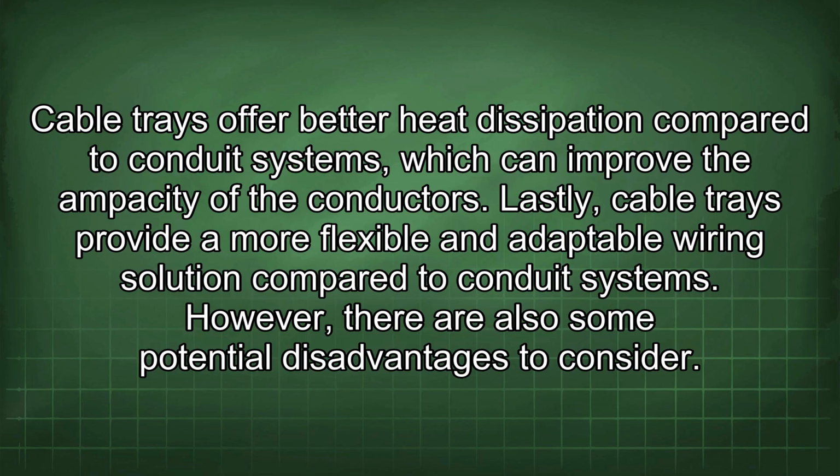Cable trays offer better heat dissipation compared to conduit systems, which can improve the ampacity of the conductors. Lastly, cable trays provide a more flexible and adaptable wiring solution compared to conduit systems.